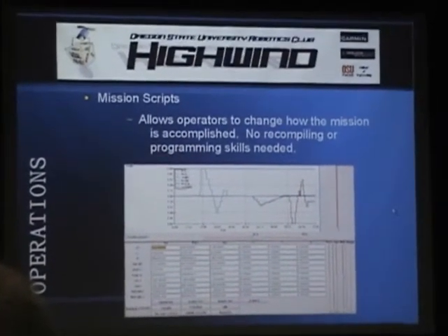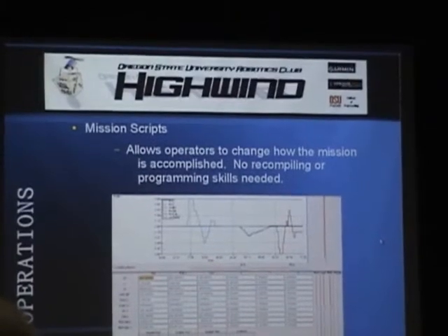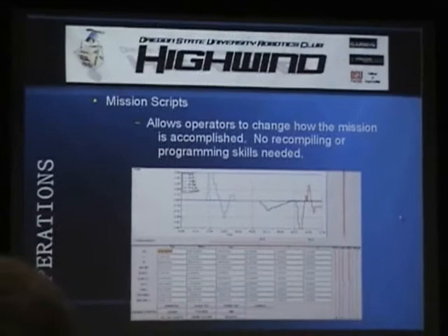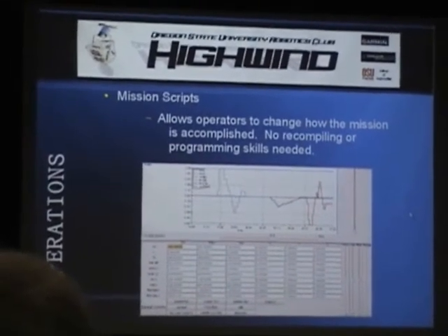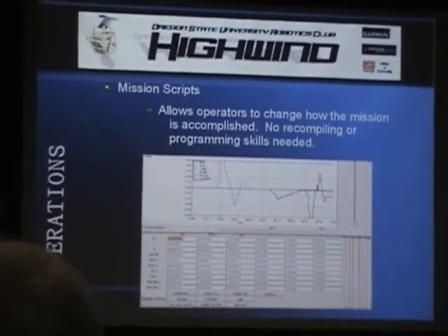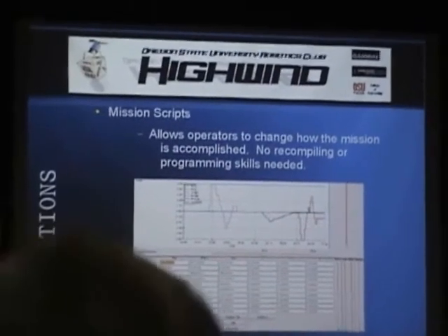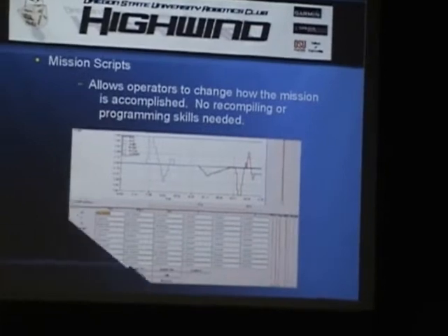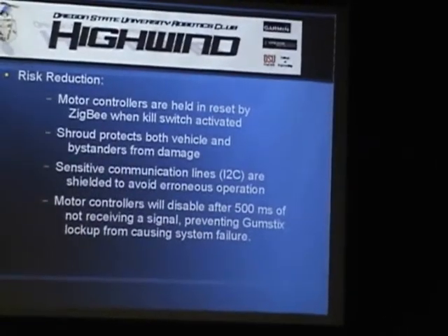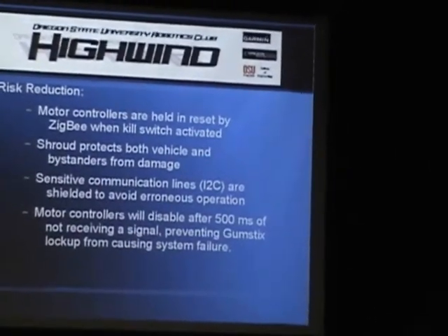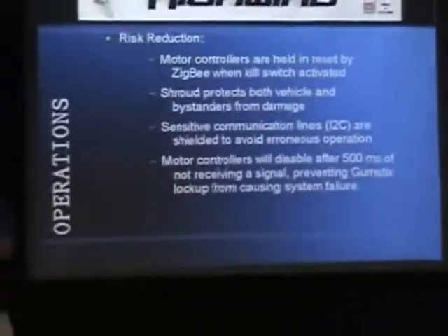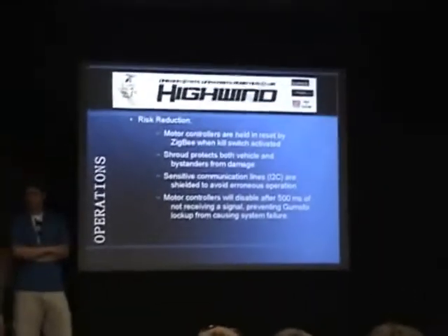And here's a screenshot of our GTK software with IMU information on it, as well as we were able to, in real time, update our PID constants and had very close and fine-tuned control over the vehicle at all times. And yet it was still running everything locally on the gumstick, so there was no latency except for updating gains and items like that.